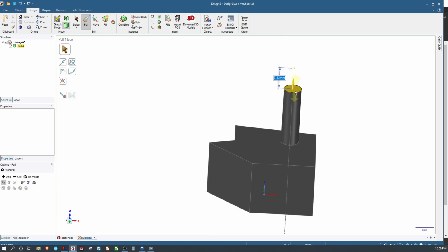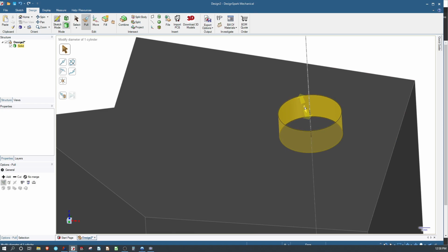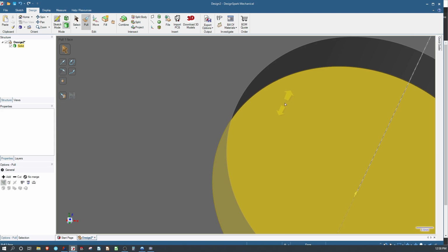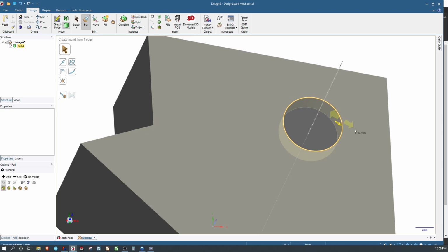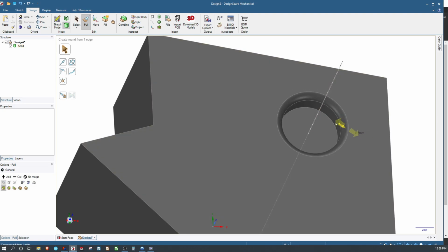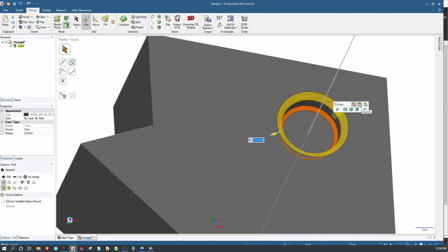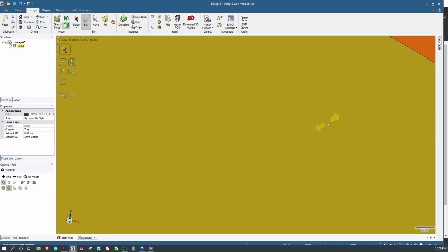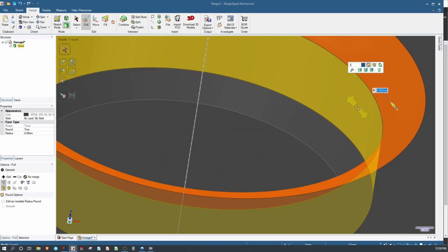So it's very interactive, and this is what we call a direct modeler because we're not using sketches as much as we are just directly modeling the geometry of these things. So I can change the size of a circle, right, just by pulling it. I can add a rounded edge onto a point. Likewise over here, I can click on that rounded edge, which we call fillet, of course, and convert it to a chamfer. And then there's my chamfer. So I can also click on this and give this a value. Maybe I want this 1 millimeter, right?